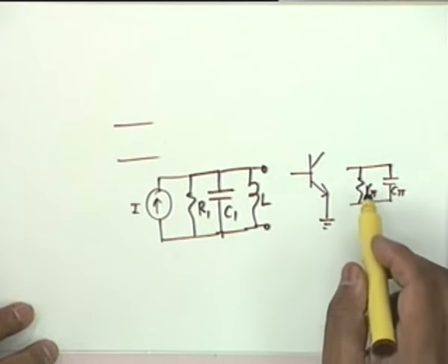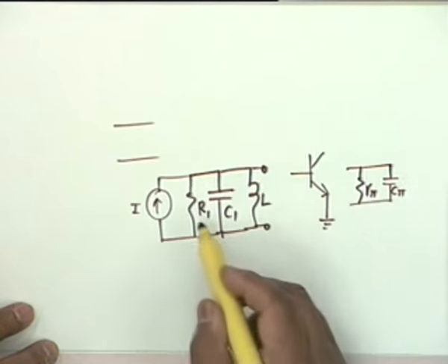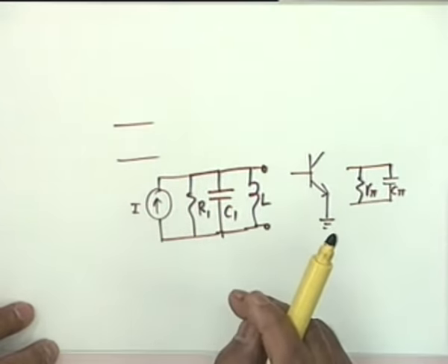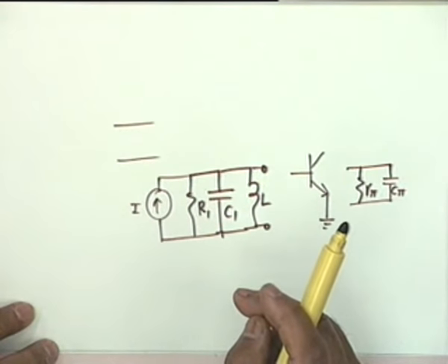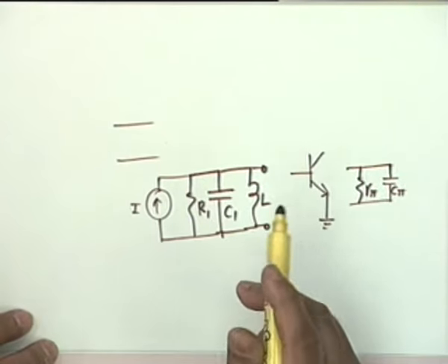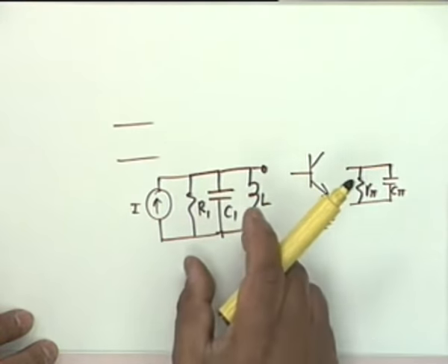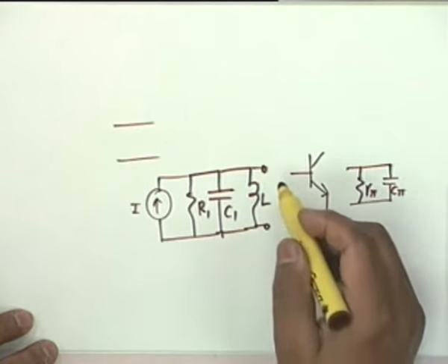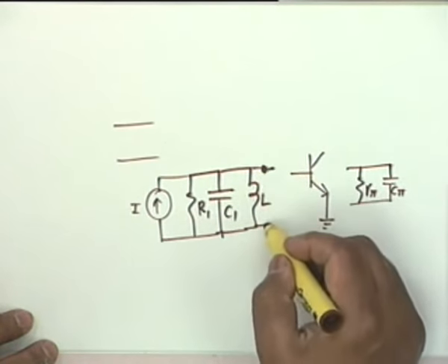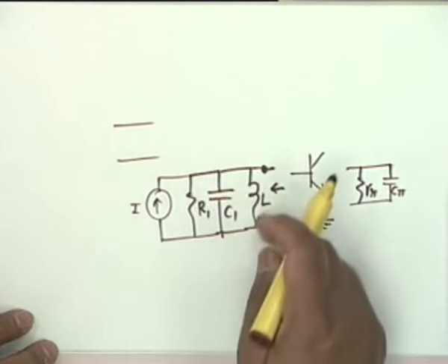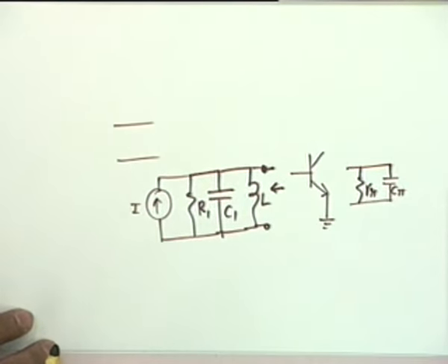Alright. Now, what is this R pi going to do? It is going to reduce the parallel resistance. What effect does that have on the characteristic? The bandwidth broadens, the bandwidth increases. It is a parallel resistance, and therefore it changes the characteristic of this tuned circuit. What you would like is a transformer from here to here such that the loading effect on the tuned circuit is as little as possible.